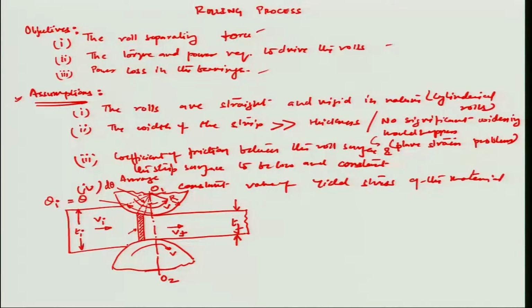Obviously, we have stresses in this particular metal roll in both these directions. This is the reaction stress sigma xi, which is trying to push the thicker material away from the rolls in the reverse direction, whereas this is the forward stress sigma fi, which is trying to pull the material into the thinner zone.